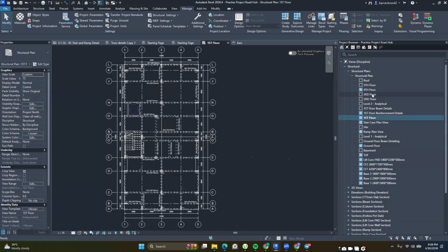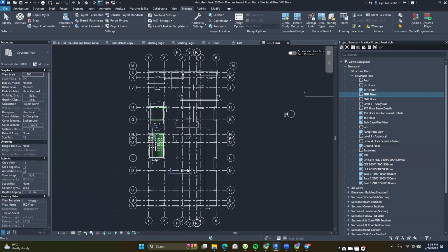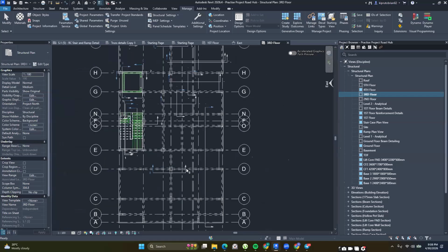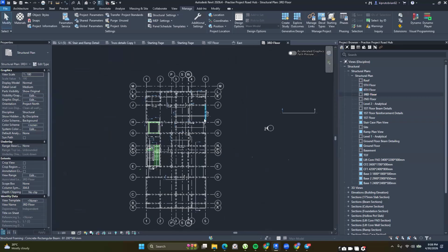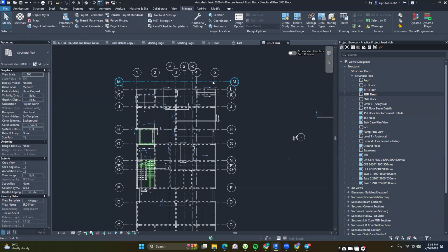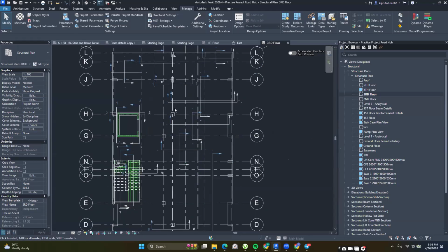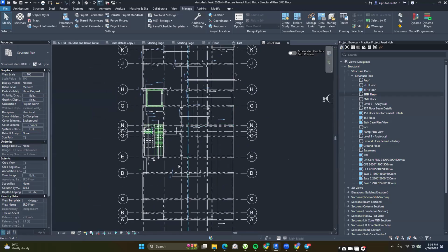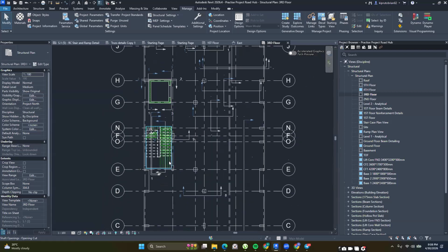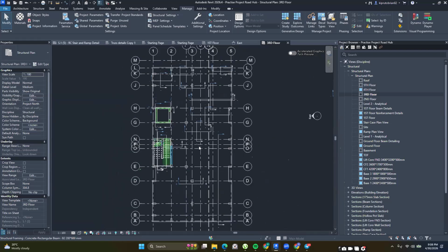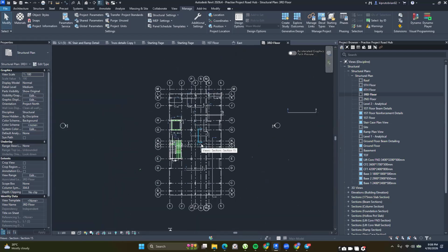And then I want you to look at a floor that was not painted. You can see how it looks. All right, you can see what we have over here. So if you look at this, number one, the grids have not been ordered in any way. All your views or your sections are visible, which is not ideal. And then your columns are not shaded, your walls are not shaded, and rebar is visible. So it ends up looking a bit dirty.